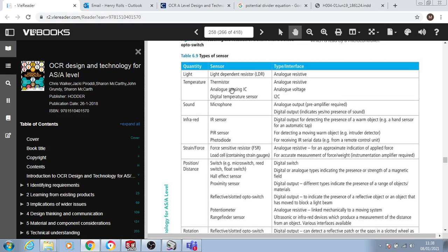So yeah, all sorts of things. By the way, there is quite a good little analogy. It's quite handy to remember which way round these two work, because these are the most common types of sensors you'll see. So light and temperature. My weird little analogy that makes me remember which way around they go is think of chocolate. On a hot sunny day, chocolate melts, and when chocolate melts it flows. So think of the chocolate as being like that variable resistor, the thermistor. When it gets hot or when it gets bright, the current flows, so the resistance has dropped. So basically when these sense light, the resistance lowers. Just an easy way of getting it round.